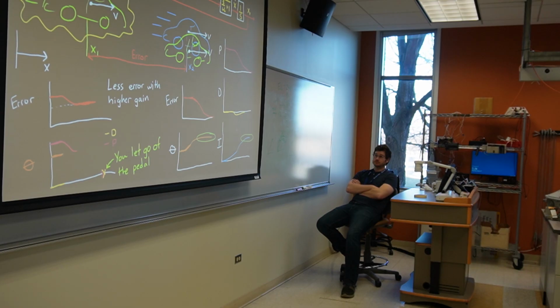And in these thought exercises, we really only looked at one of those requirements, and that is whether the error in the system eventually reached 0. However, in a real system, you tune the controller for much more than that. For example, you might be concerned with overshoot or rise time or settling time. And I'll cover how to tune PID controllers in future lectures, and we'll touch on each of those requirements and more. But for now, I hope this gave you a little bit more intuition on how each of these 3 paths in a PID controller contribute to the overall control system.